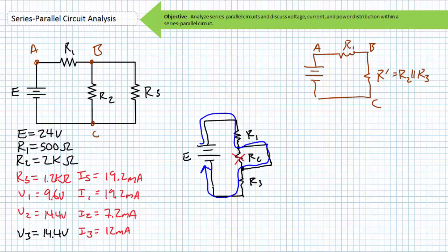With increased current draw, the remaining series element will have larger voltage drops. An open inside a series relationship will cause all current through the series circuit to cease. Since no current is flowing through any element, no element will experience a voltage drop. All voltage will be dropped across the open.